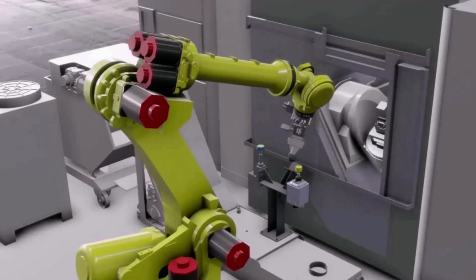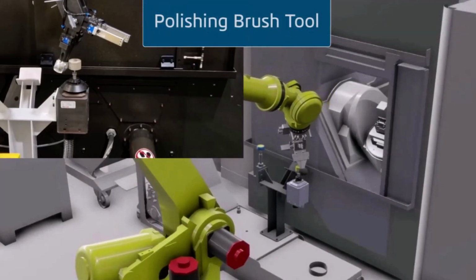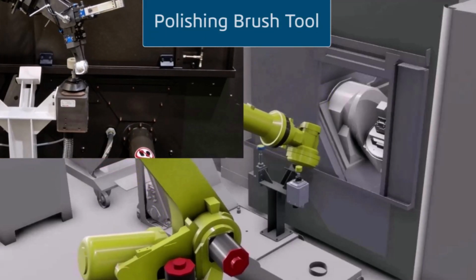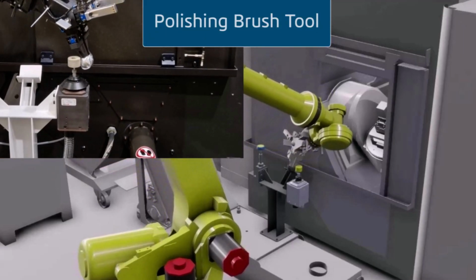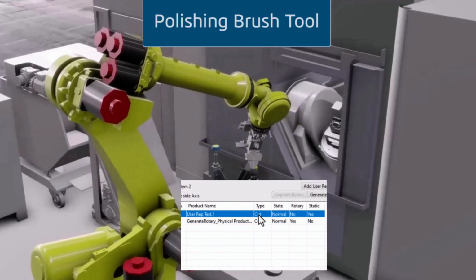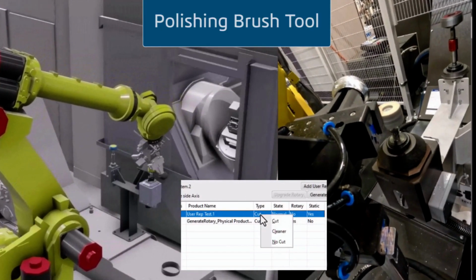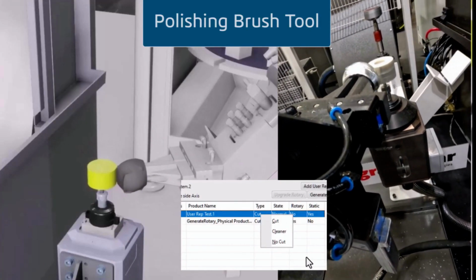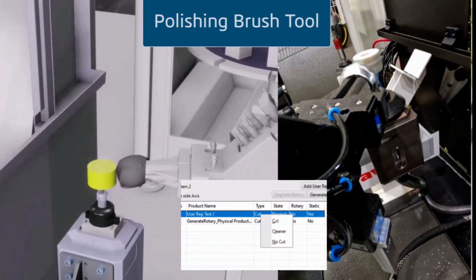Now, number 2, our second scenario is when you have a tool that behaves outside of conventional cutting behavior. Sometimes special tools like probes or brushes interact with material in different ways. Contact between surfaces can be set to no cut or cleaner type, so that the tool can be simulated to touch a part and not cut into the material.